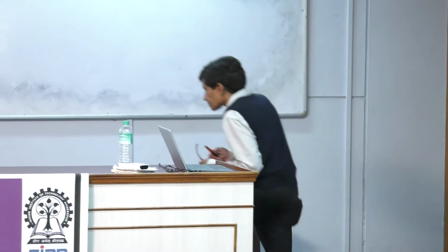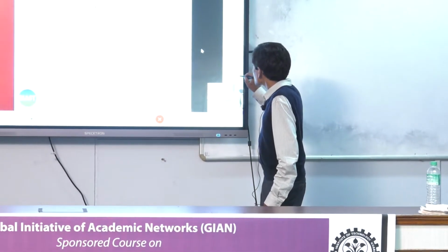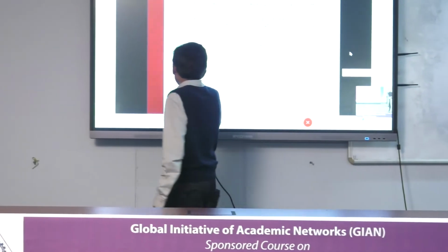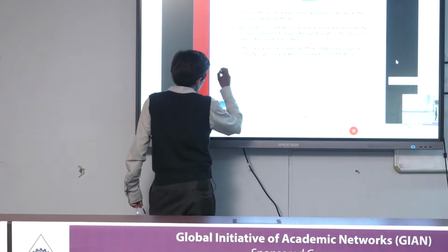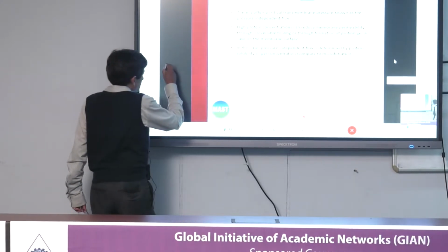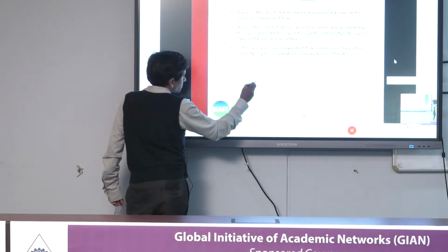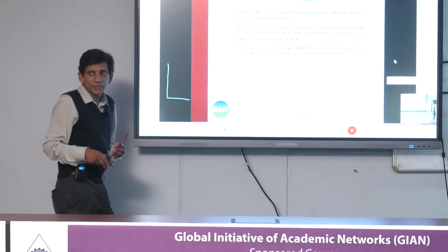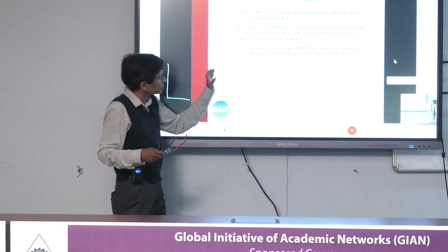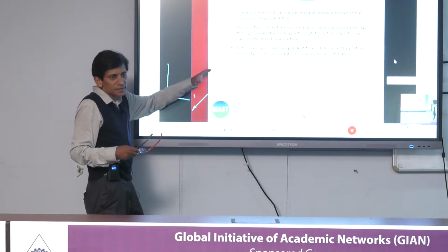Let me explain that. Okay, so what's meant by pressure-independent flux? Okay, so I pointed out that if you consider your membrane here, you have the feed coming this way and you have a permeate flow here, right? And so if you look at what's happening here, you get a build-up here and a concentration polarization boundary layer. And at some point, you'll end up in some sort of pseudo-steady state because you're pumping at a certain rate here. It's a narrowing of the channel, but that leads to dragging away of this material, and there's back migration, and this is somewhat pseudo-steady, okay?